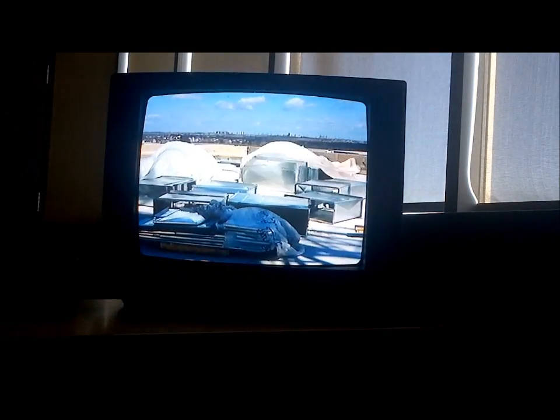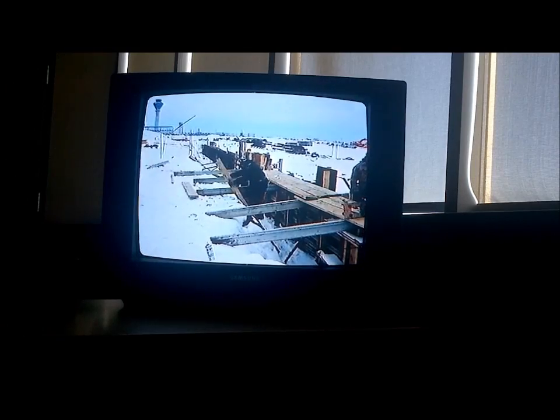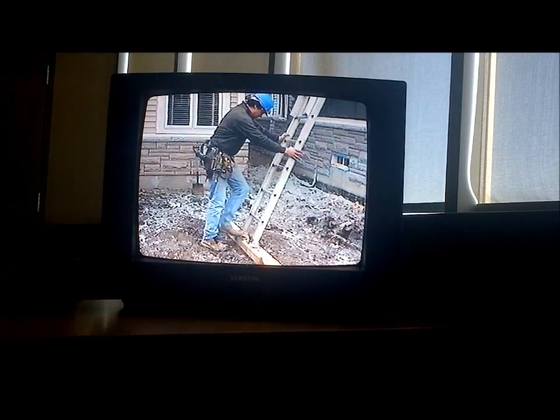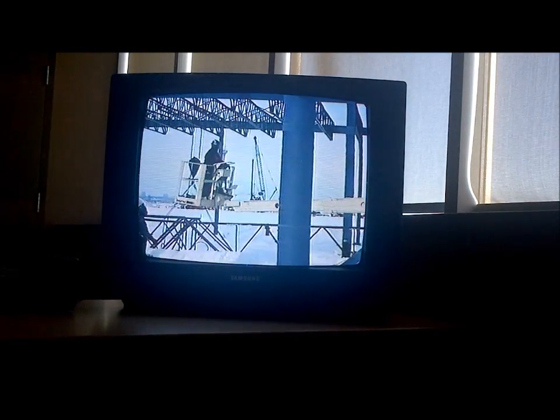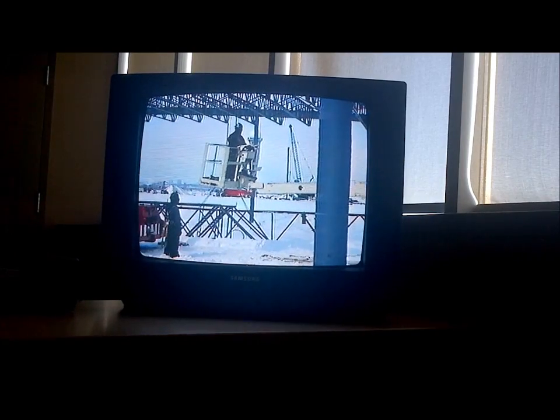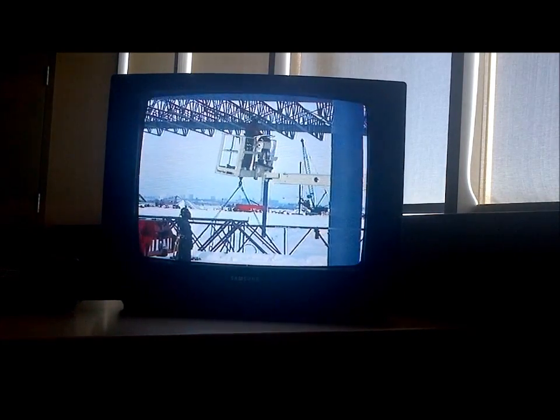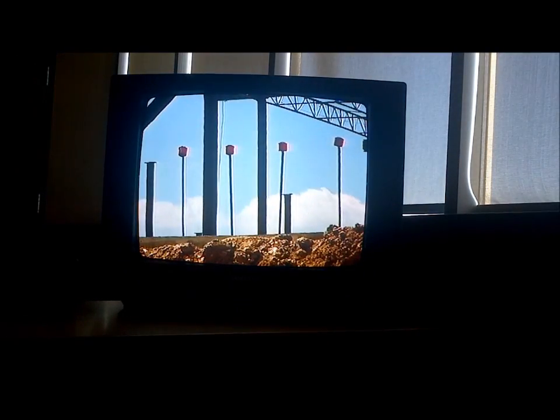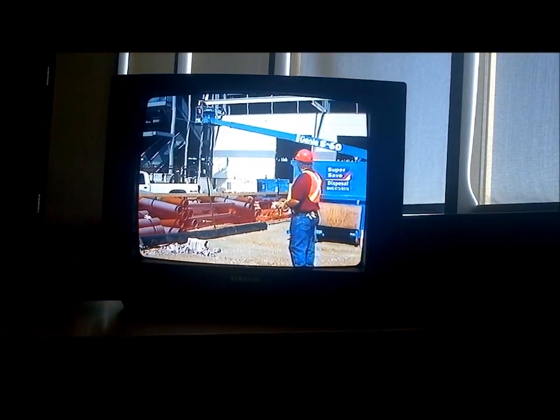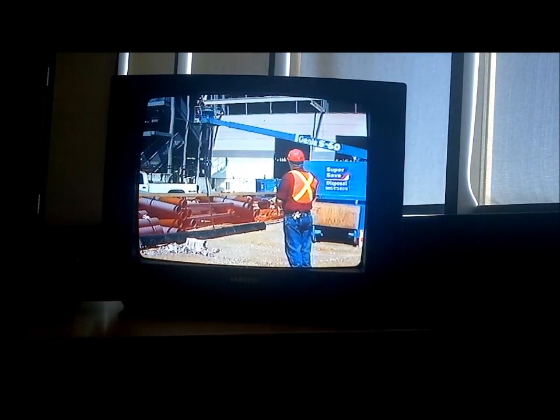All of these situations can be made more hazardous by poor housekeeping. Keep your work area clean. At heights, slipping or tripping over garbage or debris can be fatal. Poor visibility, wind, cold, rain, mud, ice can also increase the risk of falls. These are a few of the conditions and activities that pose fall hazards. Once you identify each fall hazard in your work area, specific types of fall protection can be selected and implemented.